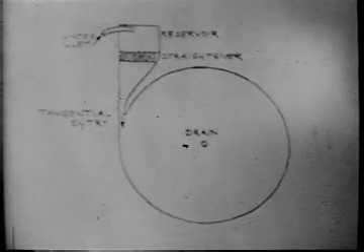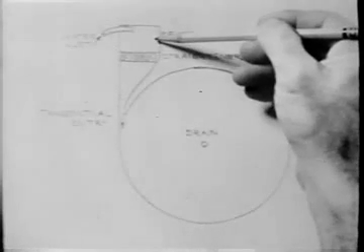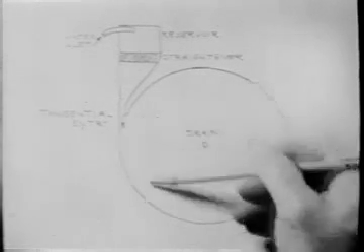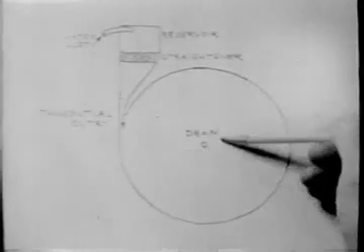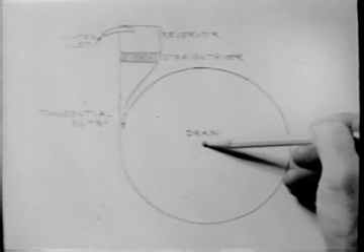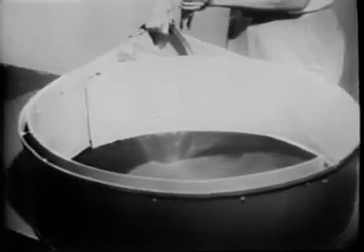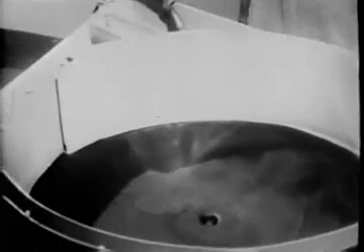On the other hand, the flow may be without rotation, even though it is curved. This is the plan view of a spiral vortex tank. Water passes from the reservoir through a flow straightener and into the tank through a tangential entry. It spirals round and round in a very tight vortex and finally leaves vertically through a drain in the center. What will the vorticity meter do? It doesn't rotate. It moves in pure translation, like the needle in a compass box mounted at the rim of a rotating turntable.